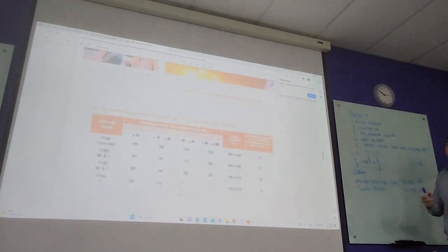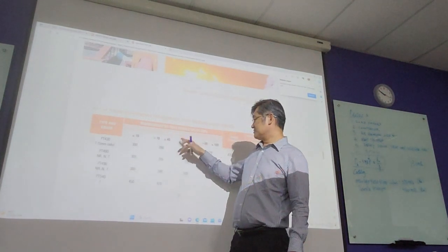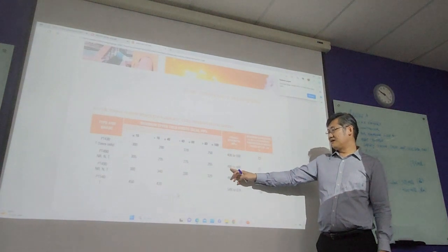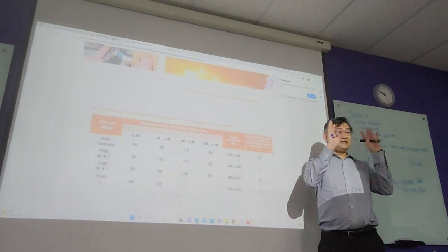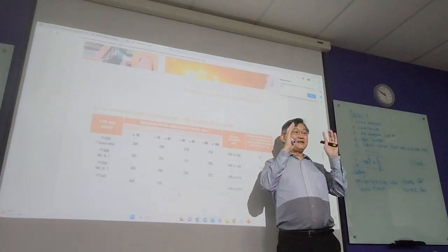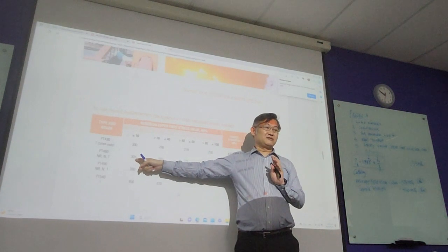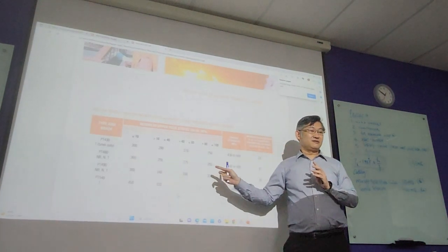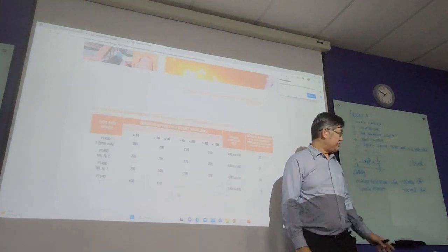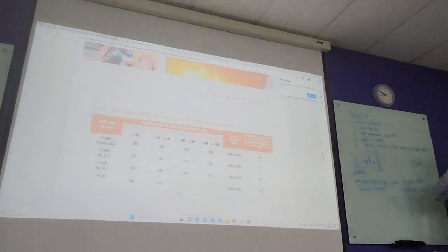Okay, now. From the catalog, the material can withstand an upper yield stress of 305 megapascal. Tensile strength withstands 460. It's not the design strength. This is the material. Design strength is supposed to be safer, right? We cannot subject our tank to this pressure or this stress. It can damage the tank, right? So our design pressure is 133. It means we add on the safety factors.